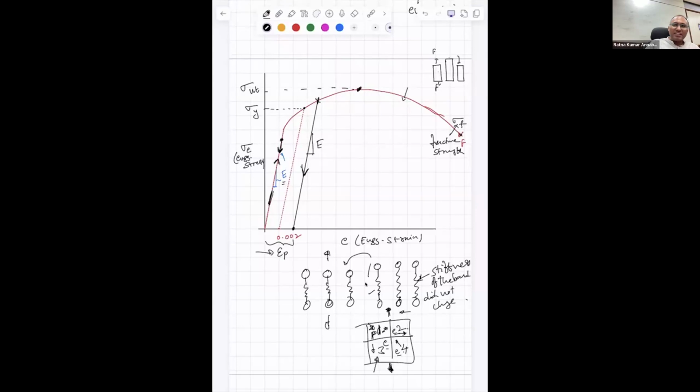That is what we call plastic strain. This is what we call permanent deformation. The material did not come back to the point O. The material has come back to, say, point P, which has some residual strain. That is what we call plastic deformation or plastic strain.